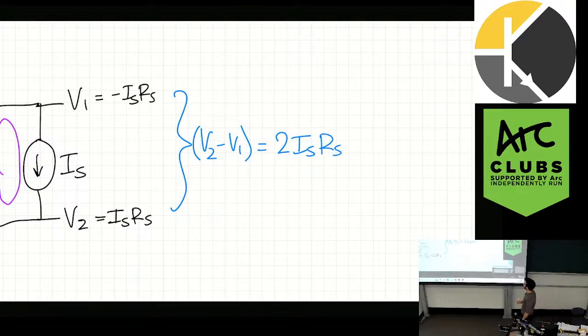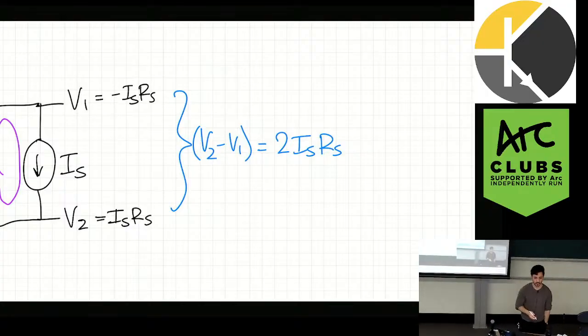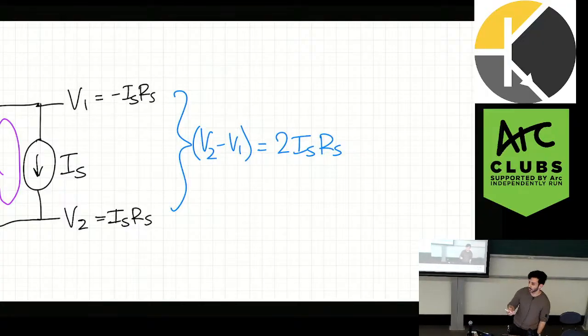Okay. So now we have an input signal. That's essentially what the circuit is doing. It's sensing a current, and that is getting converted into voltages, which are then going into the instrumentation amplifier to be converted to a signal.